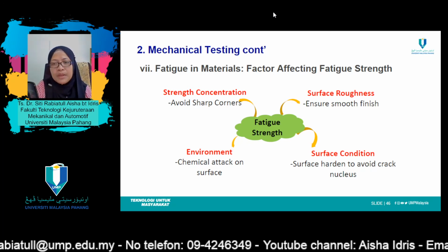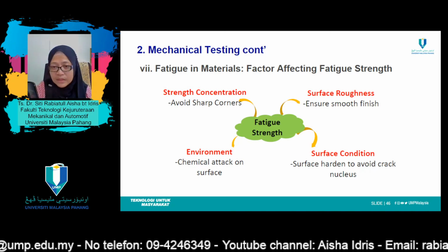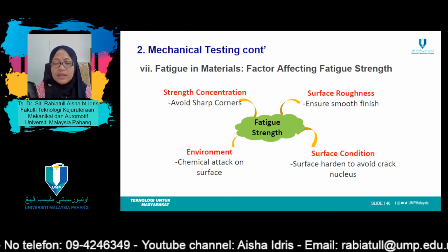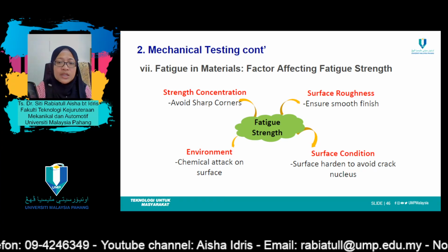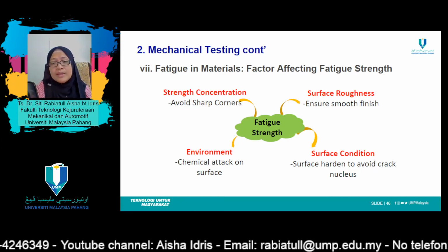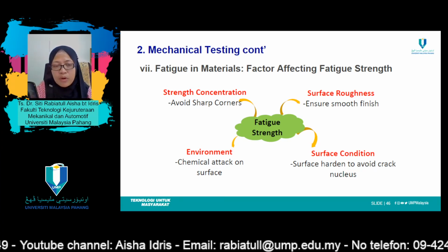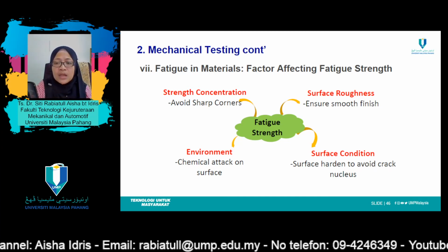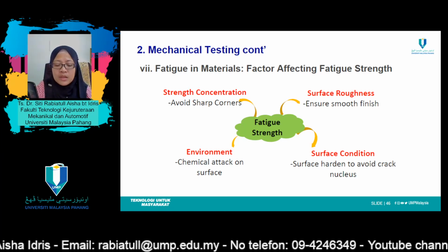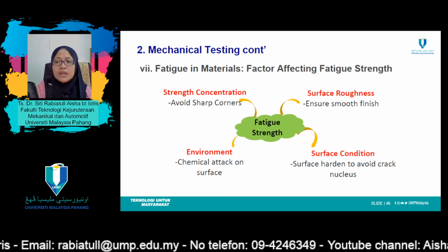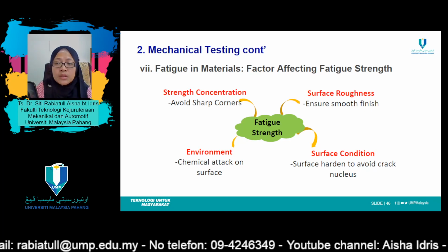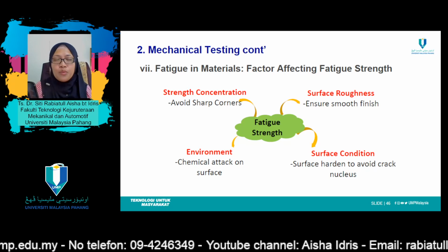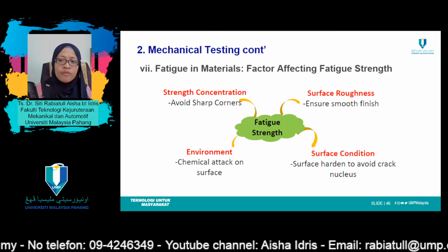Fatigue strength can be affected by several factors, which include stress concentration. That's why in any design, we need to avoid sharp corners, and use a fillet instead. Number 2, surface roughness. The specimen surface needs to be smooth, with a lower value of roughness.